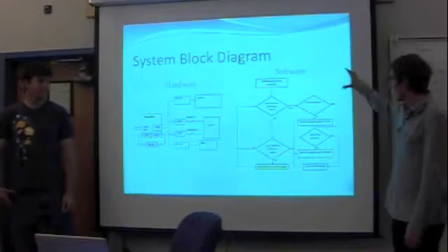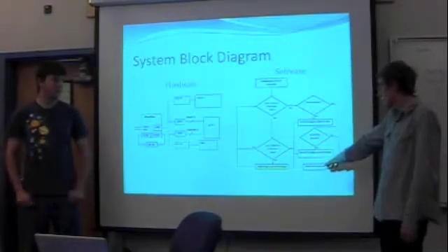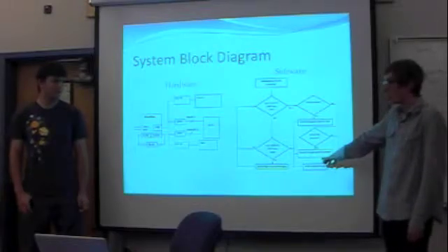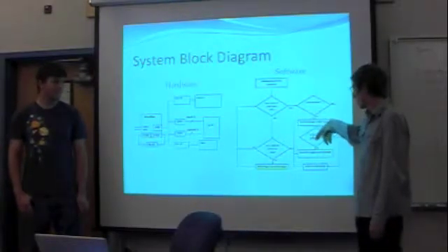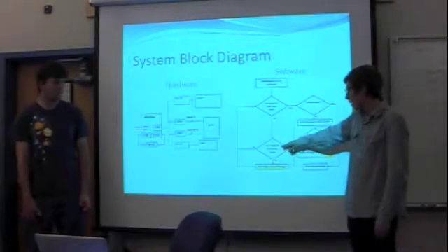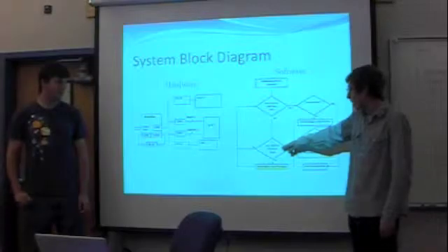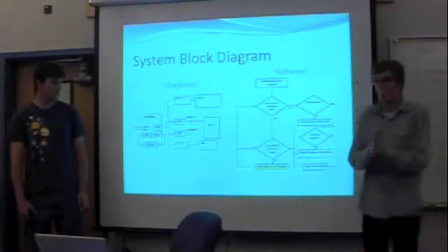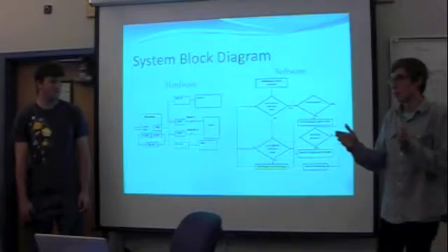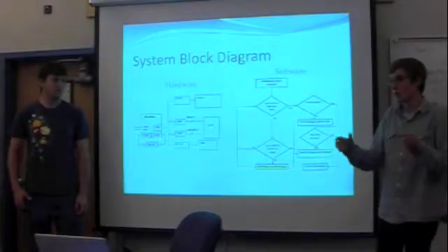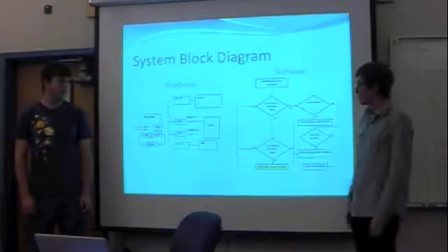And so after we're done processing the message, if it's a normal character, we just add it to the string that we're saving in the output. And then we go back through and check if the receive register of the Xbee has data. If it does, then we read that entire string, because we send entire strings at a time, and we save that into our saved messages, and then go back through the entire loop.